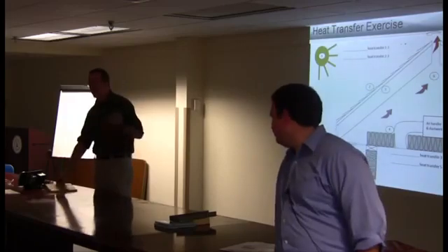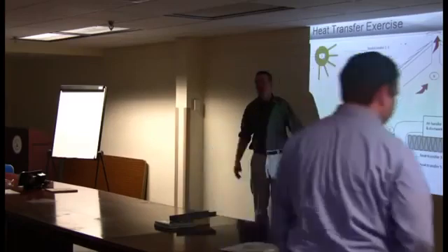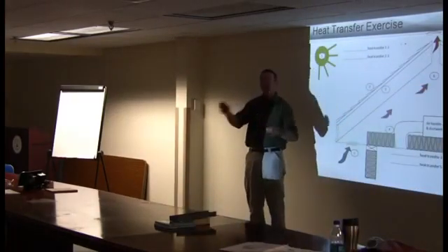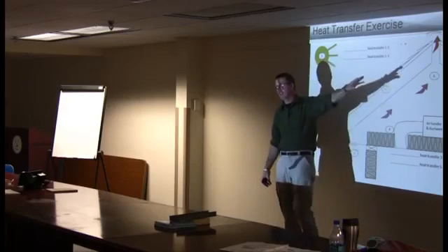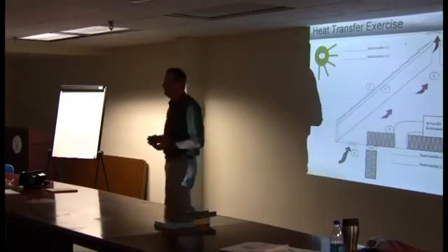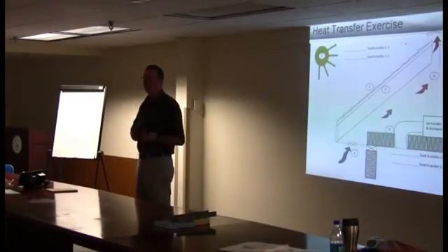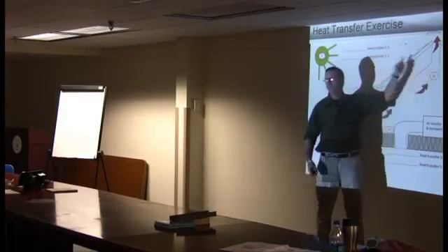But yeah, again, I'll reemphasize: if it looks like a house, it's probably more good than bad to do the standard venting. By the way, do not use a power attic vent fan. Don't use a fan. Just all passive venting. Anybody remember from the residential training, why do we not want to put a fan up here and depressurize the attic?